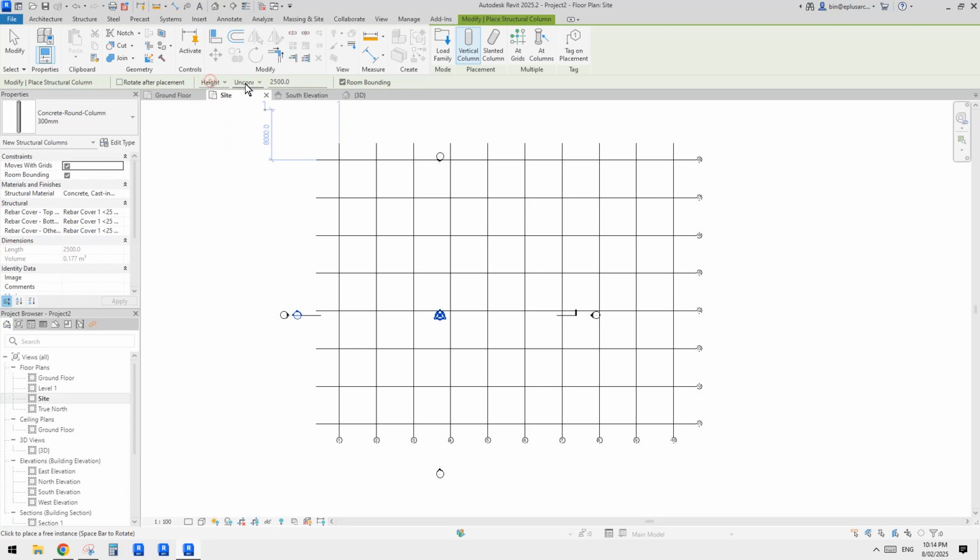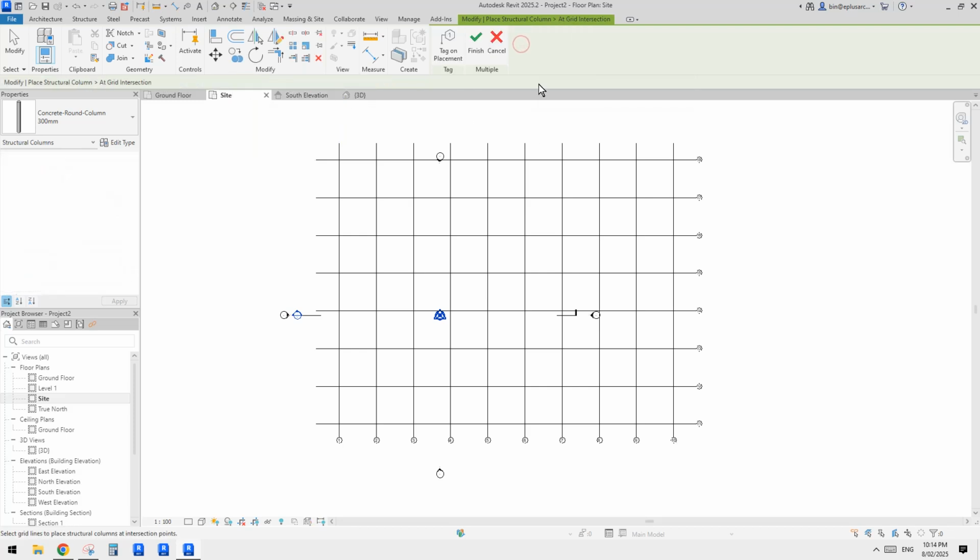So if we change this height, we can make it start from the ground level, but you can decide where you want to. Oh actually hang on, where's the base? Yeah, it's okay, we can always just place and then change the levels. So maybe I'll just leave all these settings as is, and then just click on add grids, select all these grids, right? And then finish.